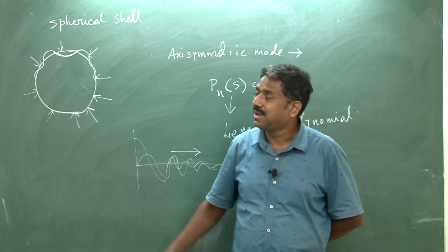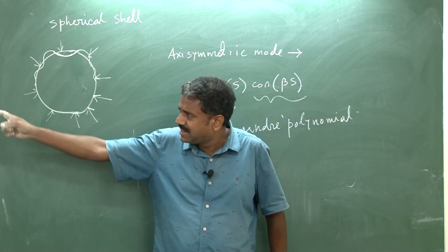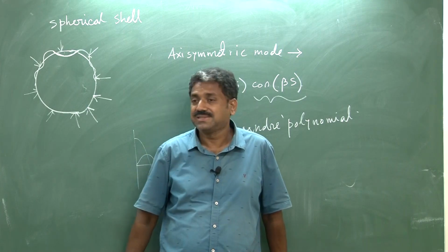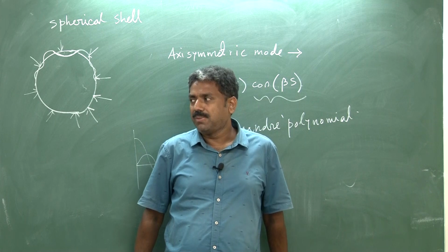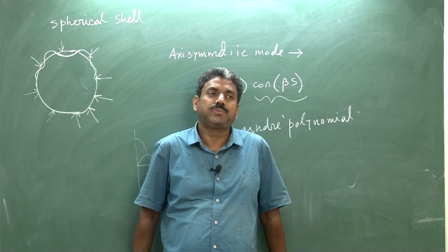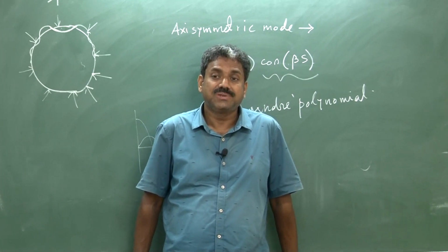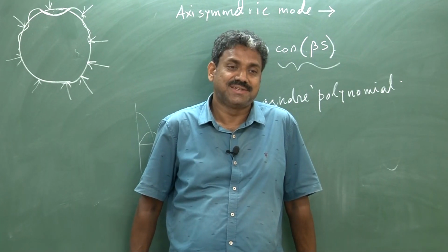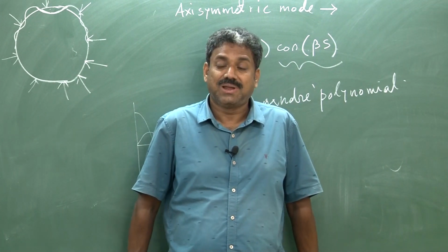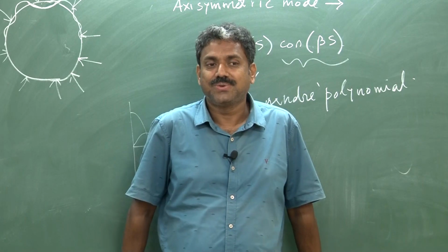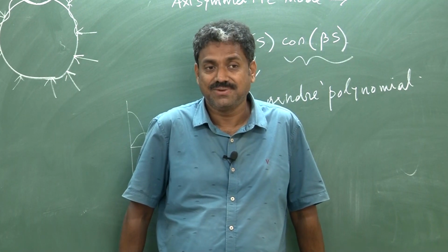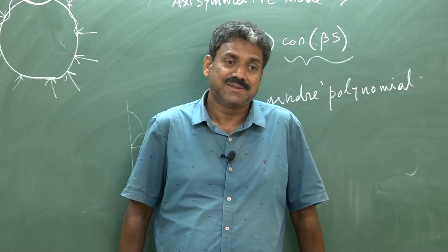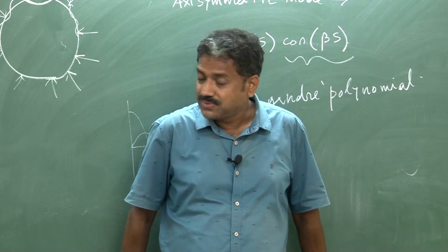You see the localization here of displacement, similarly in a cylindrical shell also localization happens in the middle. So, for the localization problem, the equation has to be nonlinear, and the equation must have a large term compared to the others, then only you can have localization, and then it also allows a very nice asymptotic or perturbation based analysis to do that localization. Similarly, you can also have